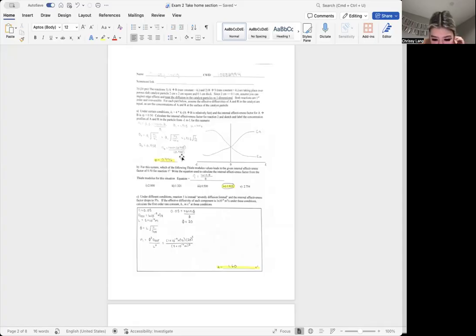And then for part B, we use the relationship to match the given effectiveness factor to the correct Thiele modulus from the list of options, evaluating tangent hyperbolic of phi over phi for each candidate. That gives a value very close to 0.5, which is equal to 1.915, which is correct. For reaction 1, that tells us that reaction 1 is moderately diffusion limited, but not negligibly, and not extremely severe either way. This value is what I then used in parts A and C.